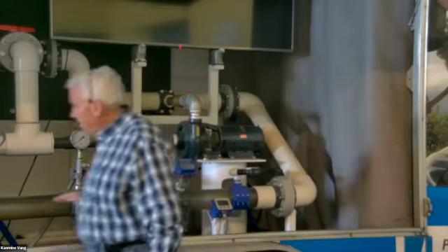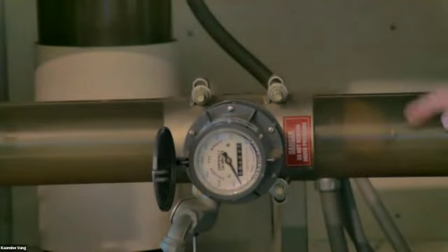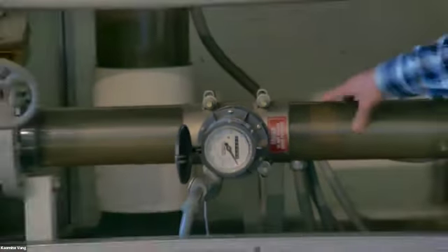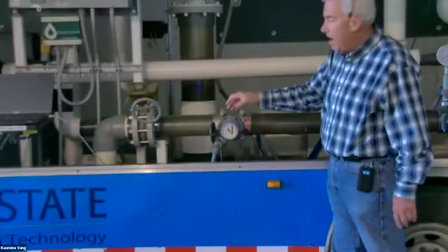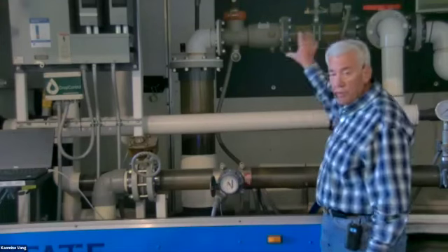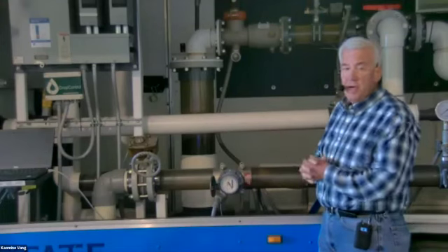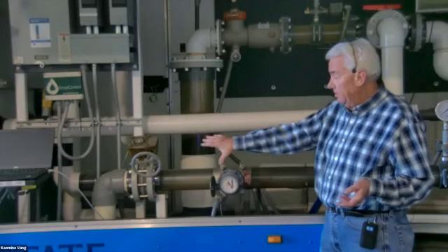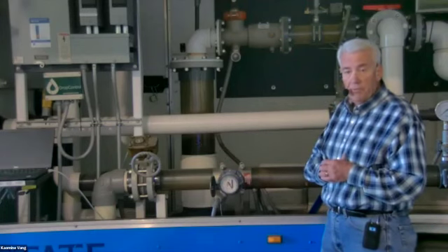Water moves on down here to our flow meter. The flow meter has a propeller here that turns. And if I close and open the valve right here and change the conditions, it'll change the amount of flow. And it'll change the pressure on our pressure gauge, and all that can be shown. And we can do that with a VFD without even closing the valve. We can change the characteristics of our pump.